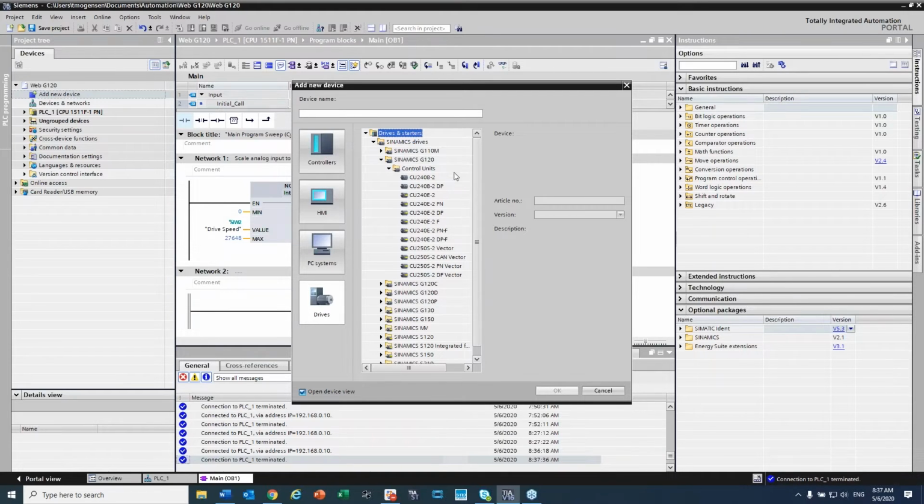And as we stated earlier, the control unit I'm using is a 240E-2PN. On the side of the control unit, on the sticker with the name tag on it, it states what version of software is in that control unit. If I would have had a little more time, I would have upgraded it to the latest version of 4.7.10, but mine is 4.7.6, so I'm just going to come in here and grab that control unit.